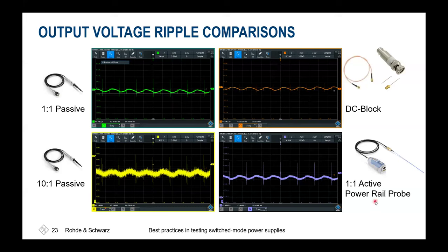That's why for a certain while, these so-called power rail probes are available. The probe itself is a transimpedance converter, which is housed into this box here at the bottom. We'll have a coaxial cable, which could be connected to a solder-in. So that's a coaxial cable where you'll have the center pin available and the ground connection, and then could easily solder that into your design at the certain test points. With this, you'll get coupling bandwidths of 2 to 4 gigahertz and an offset range between 60, 70 volts, depending on the model.